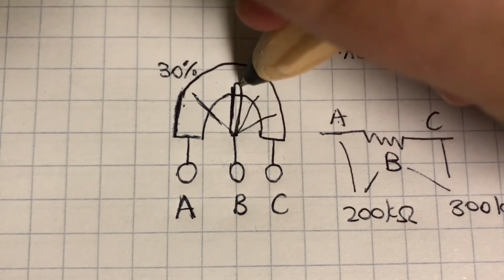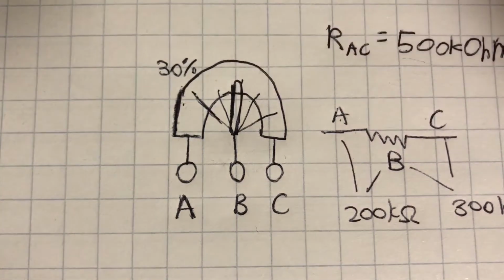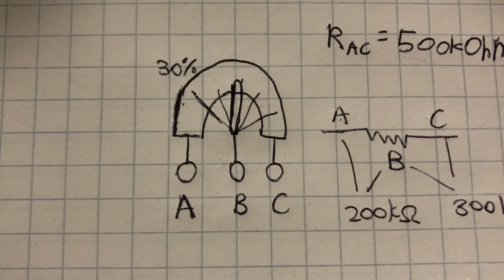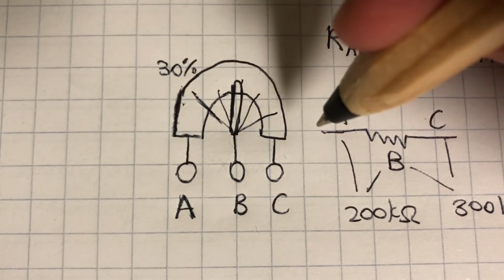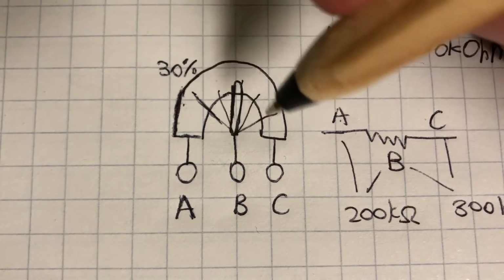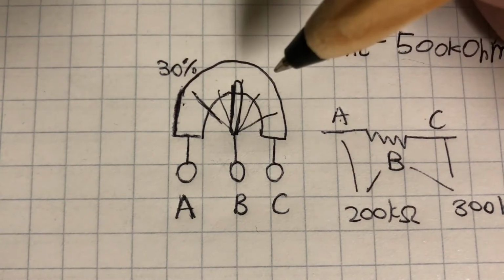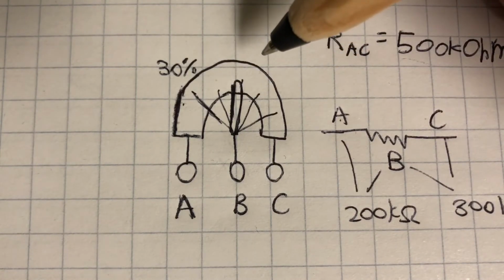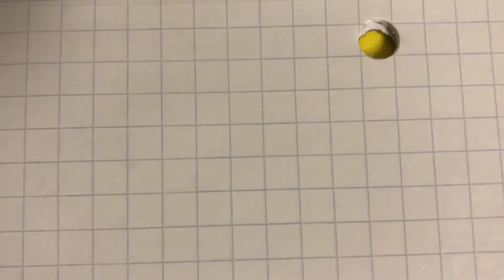So I hope you're starting to see how the adjustments are working here in terms of taking a fraction of the total resistance, because that's basically what this device is about. It's meant to be used for taking just a tiny fraction of it when we need a certain amount. So now let's draw what we saw before on the circuit diagram, but only isolating the volume control.